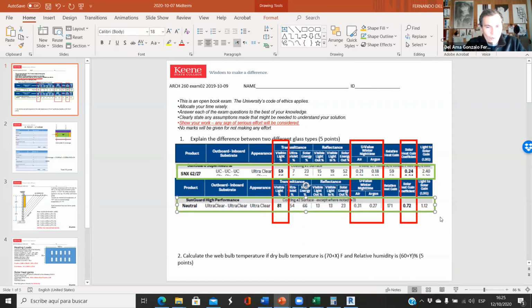I would be even more precise now: I would use this for the south facade in a cold climate with a lot of sun hours, because if we are working with a northern facade, I don't need these solar heat gains, since we won't have any sun in the north. So I would use this first one for Florida or California, and this one for New Hampshire.